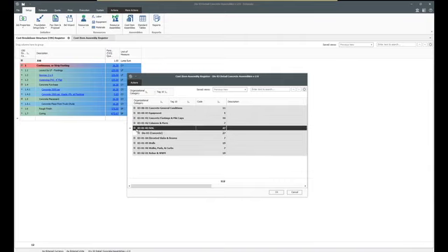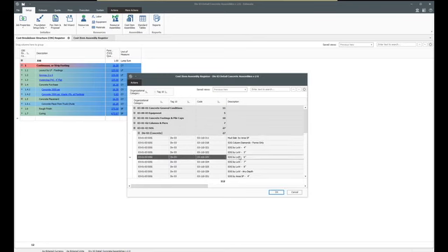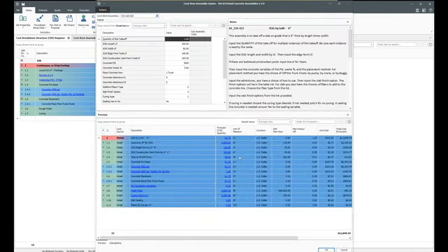So we'll go get a slab on grade, and in this case I'll get a 6-inch slab on grade. The questions will be slightly different. The questions now are about slab on grade issues instead of footing issues. So what is my length and my width of the slab on grade? I'll say we have something that's 75 foot by 45 for whatever reason.